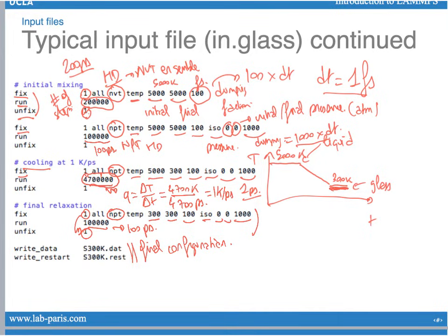This is important because if you want to continue this simulation further or do a new simulation that is now applied on the silica glass that you just generated, you don't want to keep redoing the same simulation over and over. What you want to do is to perform one simulation to, in this case, make a silica glass, then save the final position of the atoms, the configuration of the silica glass, and then possibly for a next simulation reuse as a starting point this new configuration that you just generated. You don't want to keep redoing the same simulation over and over.